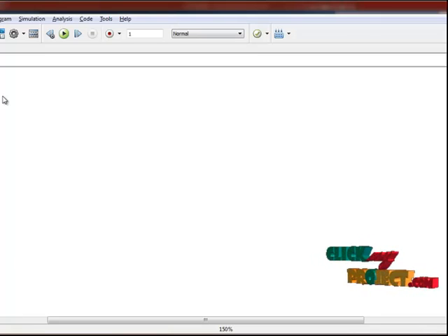After finishing the process completely, one important component we need is the powergui. We use the powergui because this simulation tool needs it to supply power to the whole panel. Using the powergui, we can get, for example, the three phase AC and DC source. So this is important for the powergui. After finishing, just click the run button, and then we get the output in the scope model.